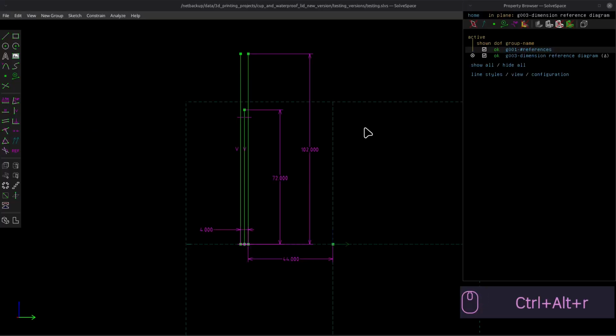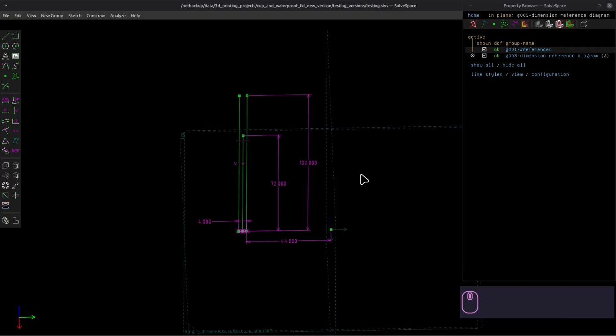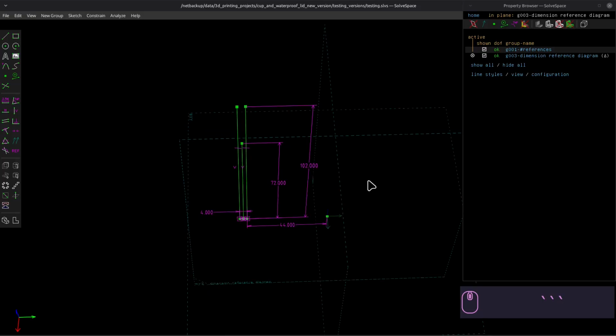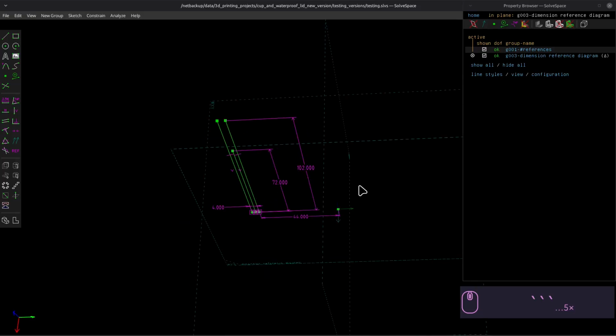Okay, we're going to do the handle top sketch. And the handle top sketch needs to be positioned on a drawing plane that I specify by rotating this diagram with the top toward me. By the way, there's a way to get a perspective view of what's showing on the screen, and I've just turned that on so it's a little easier to figure out what's going on.